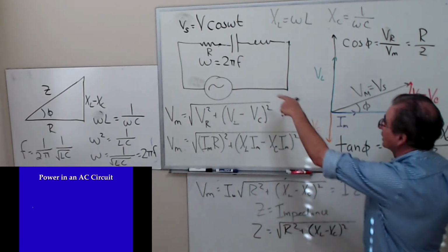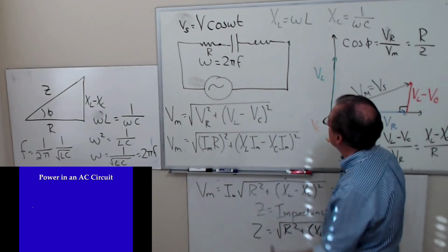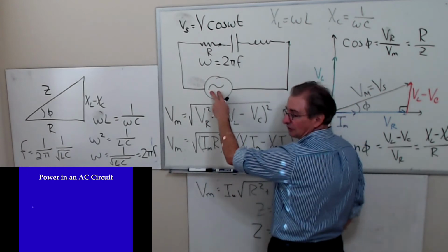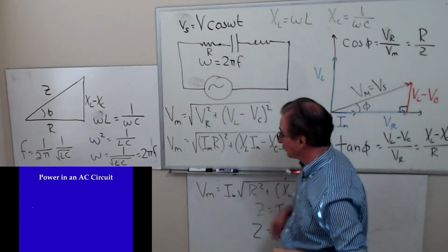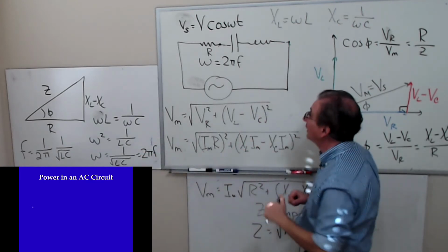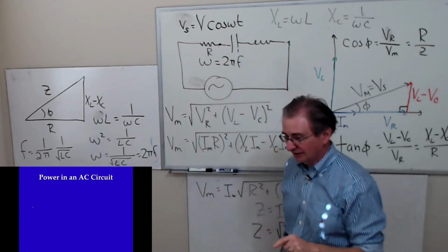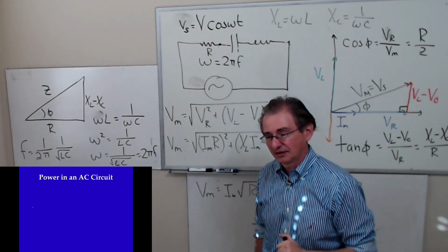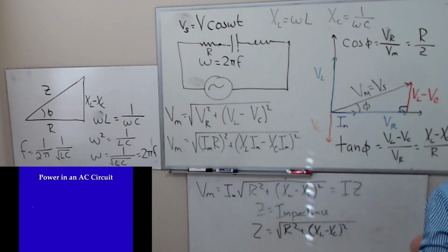You're going to actually set up this circuit, and you're going to be measuring the voltage across each one of these. You'll set this to, let's say, about 2 volts. You'll find frequencies, when you adjust the frequency of the signal generator, where the voltage across these guys is bigger than the power supply voltage. That's okay. You're still conserving energy.